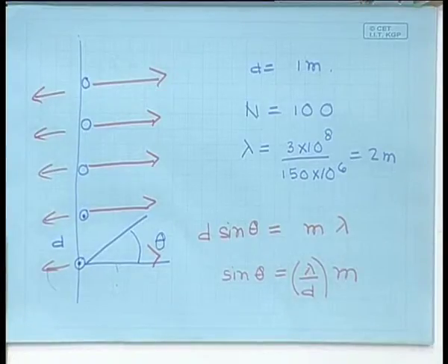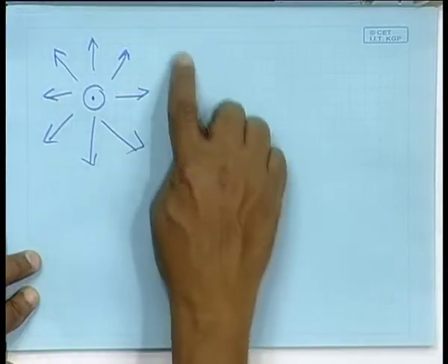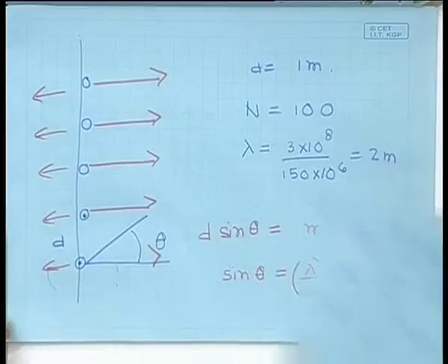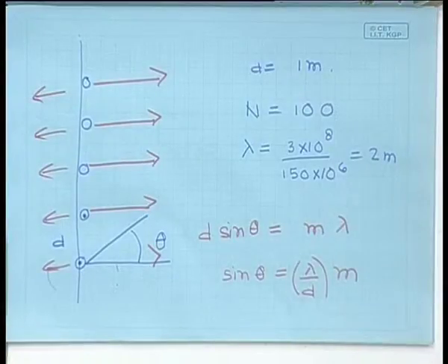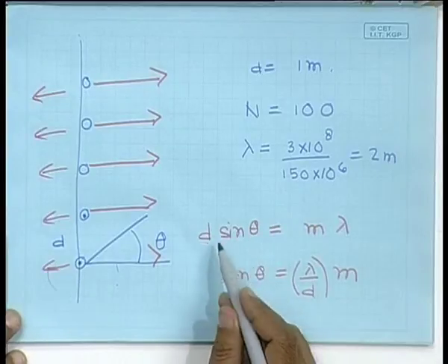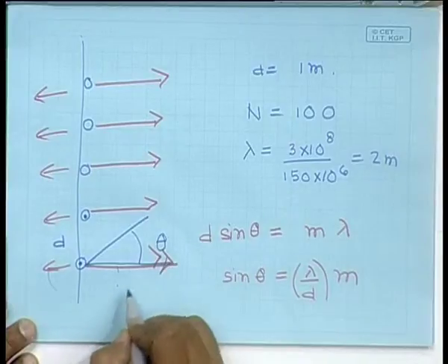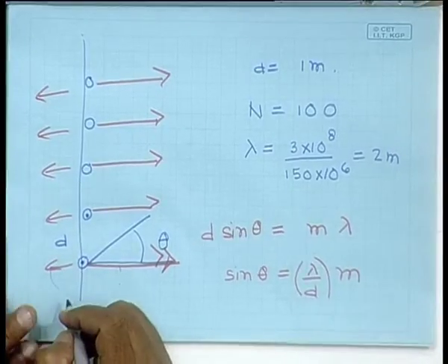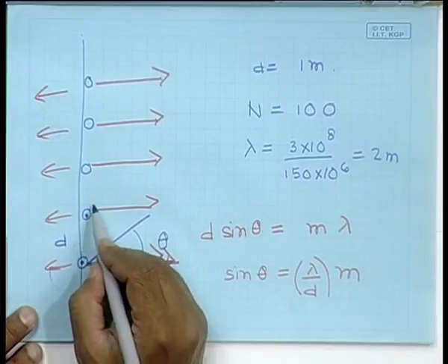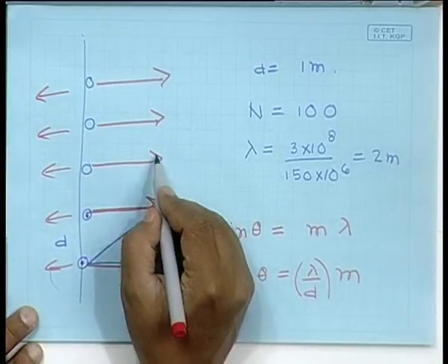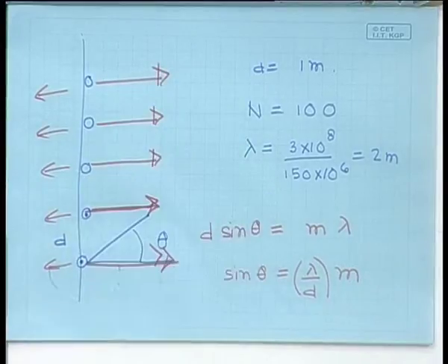So, what we see is that when we have only one dipole, it emits radiation equally in all directions in the plane, but now when I have an array of 100 of such dipoles, the radiation pattern has maxima. In this case, there is only one maxima in the forward direction and one in the backward direction. So, the bulk of the radiation goes out towards the direction theta equal to 0 in the forward direction, in the backward direction theta equal to pi. And so, you have been able to introduce a definite directional dependence in the radiation from this whole configuration.